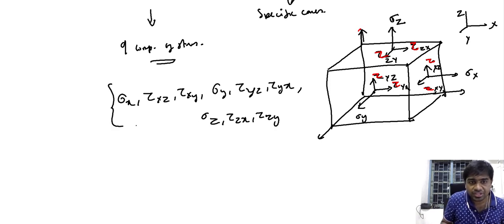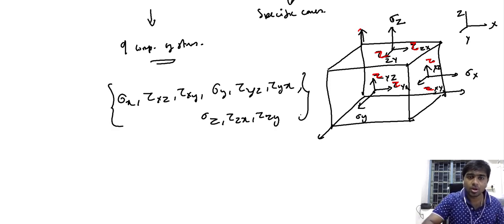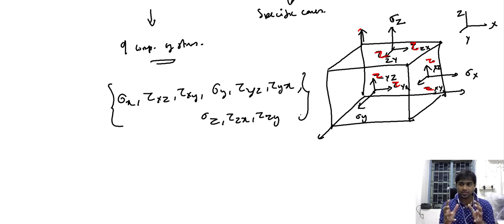What we have essentially done is we have written down all the possible values that the stress could assume depending on the indices. So we have shown that for a generalized case of triaxial loading, when we focus on a plane that is inclined, we need 9 different components of stresses to describe the mechanical condition experienced by the plane.